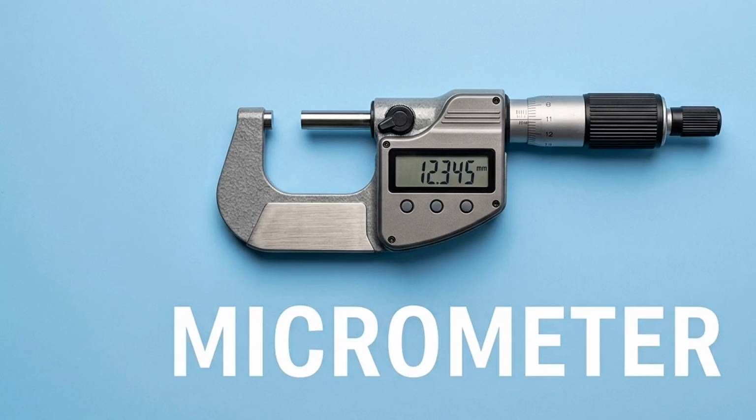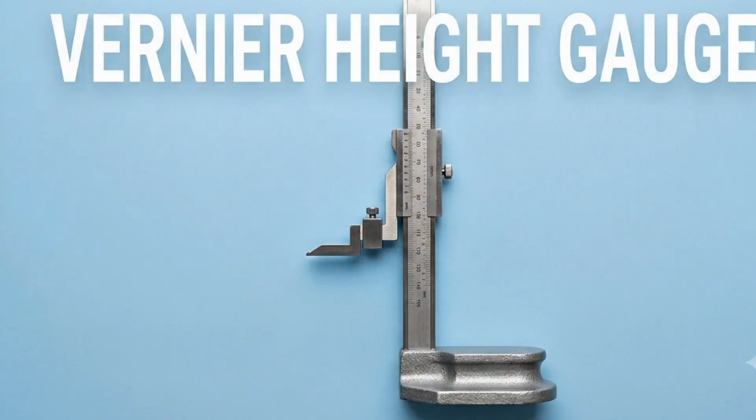Even a tiny error can affect the performance of mechanical parts, making the micrometer indispensable. A vernier height gauge is used to measure the height of objects and to mark precise horizontal lines. It is mainly used in engineering workshops and manufacturing plants where high accuracy is required. The tool slides vertically along a precision scale, allowing users to take consistent and repeatable measurements.